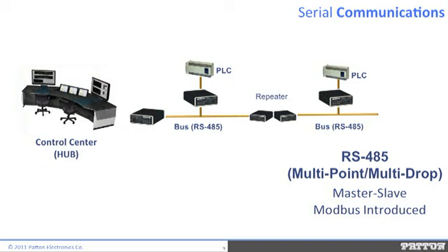RS-485, now known as TIA-EIA 485, became immensely popular. It still is. Like RS-422, the standard defines only the electrical parameters. However, it led the way by being the physical infrastructure for using communication protocols in industrial applications. You'll probably all recognize one of the most popular, Modbus, which was designed for use in RS-485 networks.